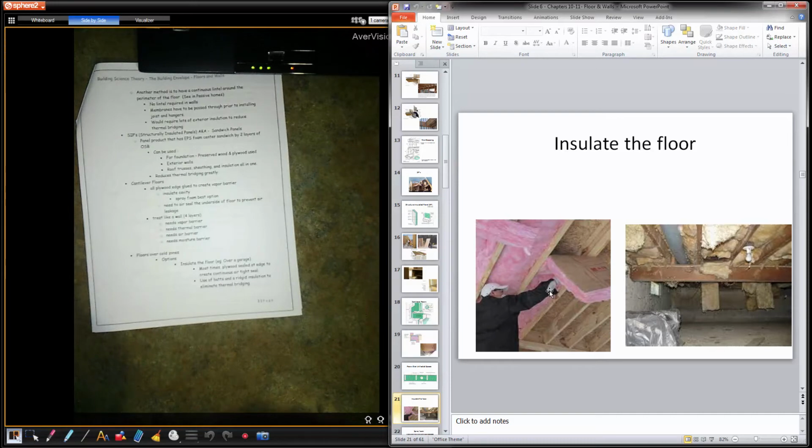So a lot of people, when they're doing a ceiling, they'll put the insulation in and they think they have to put poly here. If they put poly on the underside here, they're now trapping moisture. Vapor goes on the warm side, right? So where this guy's standing, he's in the cold part. So it's kind of the backwards way of insulating. So you have to make sure you really, really understand what you're doing there. Where does vapor go? Vapor goes on the warm side. And on the cold side, we have to then stop moisture from going in and possibly air.